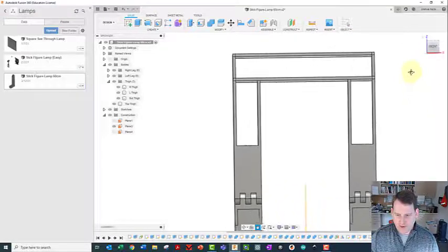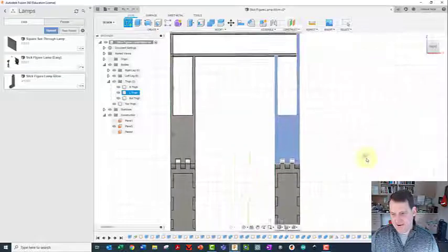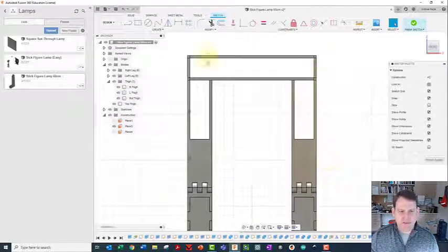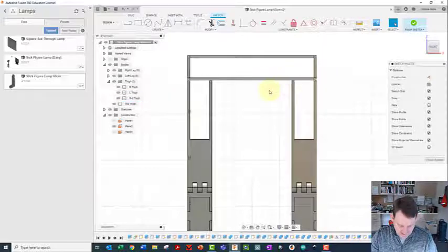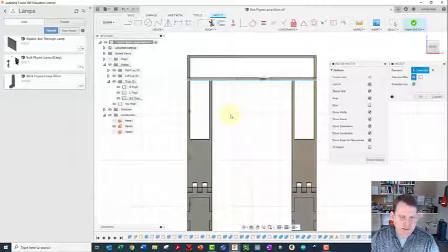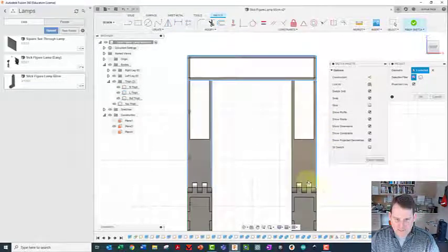So then I'm going to go here. Now I'm going to do the front of it, right? So I'm going to do overlapping rectangles for all of this. To do that, I'm going to want this line here. So I'm going to project this line, this line, this line. Actually, I'm going to just do all of these lines, and that will give me sort of what I'm looking for. And I'm going to say, okay.